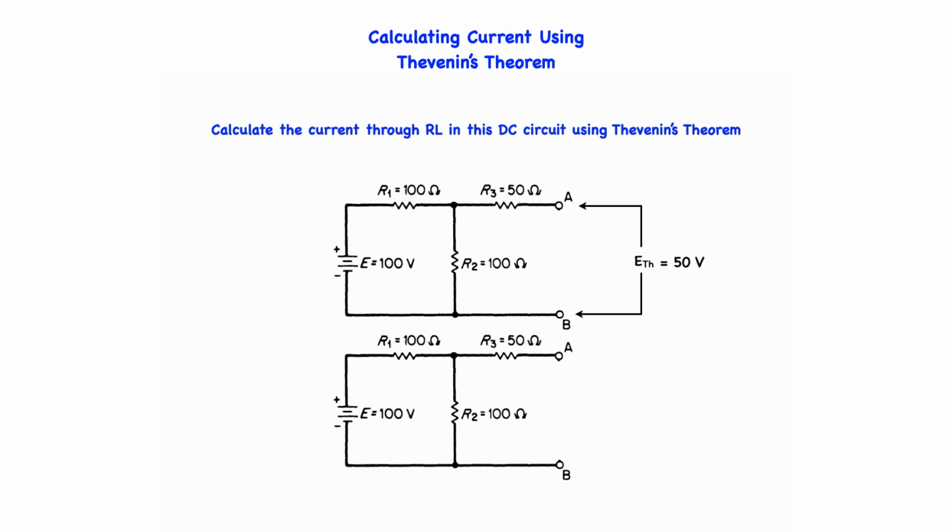Next, when Thevenizing the circuit, we find the Thevenin resistance, RTH. The network is redrawn with the source of EMF replaced by a short circuit. If a current source is present, it would be replaced by an open circuit. The resistance of the redrawn network, as seen by looking back into the network from the load terminals, is calculated.